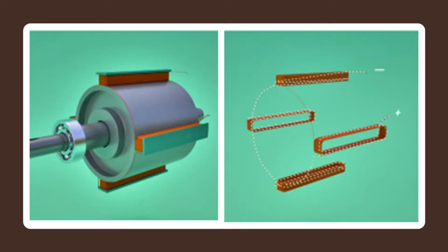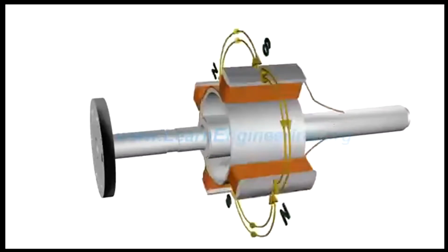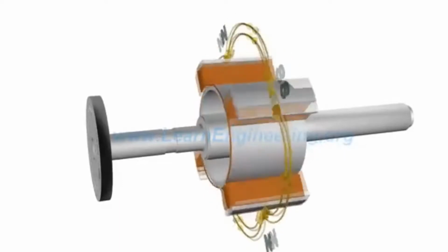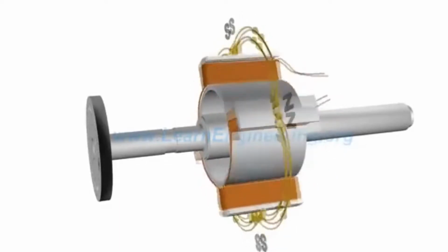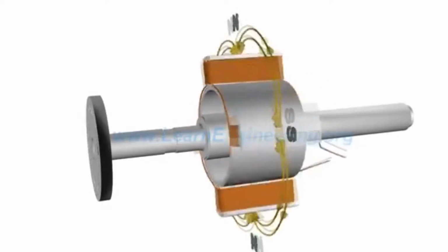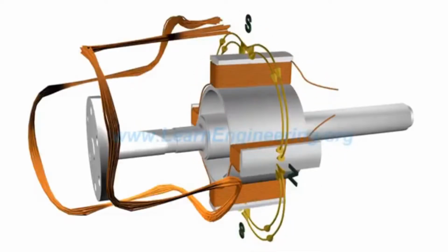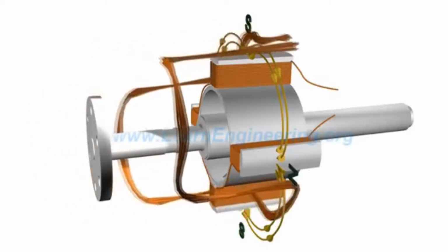For gaining better insight into its working, let's consider a rotor with just 4 poles. Rotor coils are excited with a DC power source. The rotor is made to rotate by a prime mover. This makes the rotor flux also rotate along with it at the same speed. Such revolving magnetic flux now intersects the armature coils, which are fitted around the rotor. The magnetic flux will generate an alternating electromotive force across the winding.